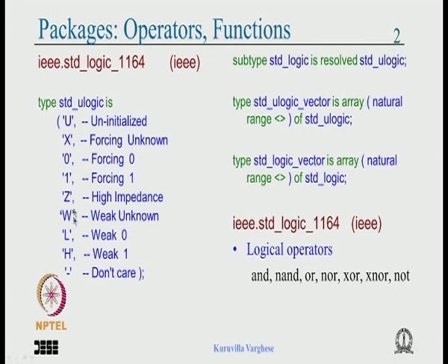Standard U logic takes all these values. Standard logic is a resolved standard U logic, that is, it resolves multiple drivers. Standard logic vector and standard U logic vector are unconstrained arrays, and what is extra defined in this are mainly the logical operators in standard logic 1164.